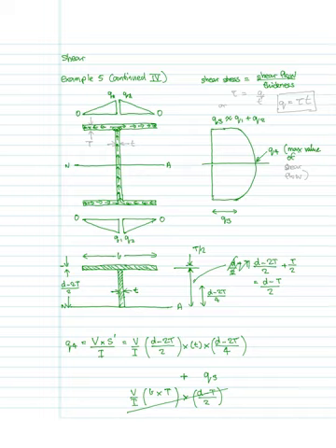So that's just to show that Q4 can be obtained by adding the first shaded area onto Q3, and that would give you the maximum value. So that would be the max value of the shear flow. And remembering that the shear stress is equal to the shear flow divided by T, or the shear flow is equal to the shear stress multiplied by T.